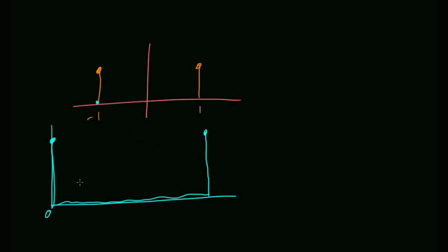You can imagine there's almost like a little reflection point in the middle. You start here, you travel to the right, and when you get to the end of this axis, it turns around and continues plotting, and then it's basically almost 0 again. It's a long story, and it just has to do with the way the FFT math works out. But it's a total pain in the butt. Looking at this doesn't help you at all. So we have two problems. One is that we didn't get a frequency vector. The other is that our FFT kind of came out backwards. We got the positive frequencies, and then we got the negative frequencies, and it's just weird. It's not hard to fix.